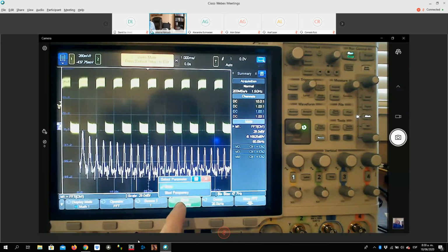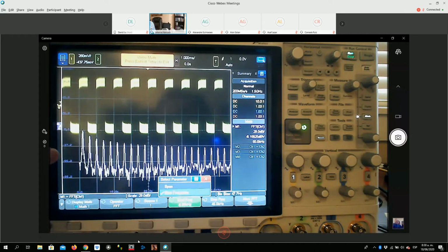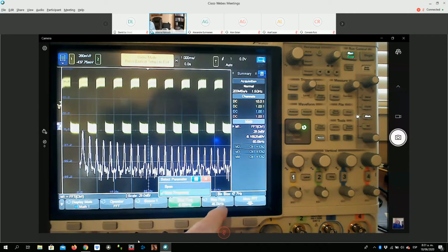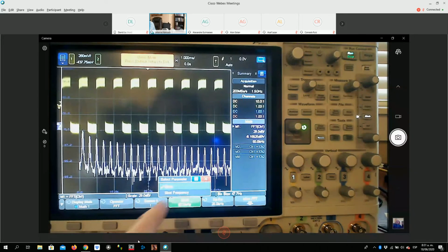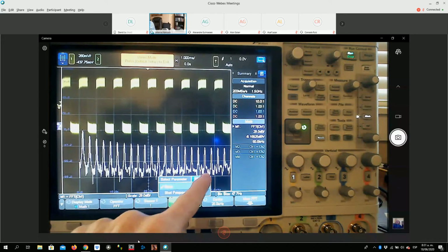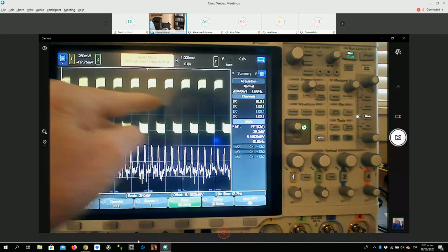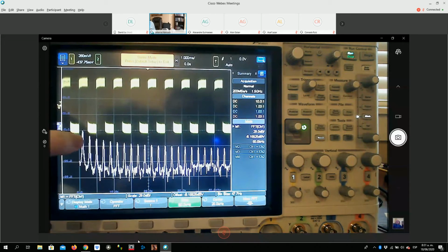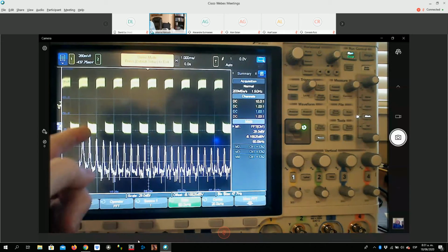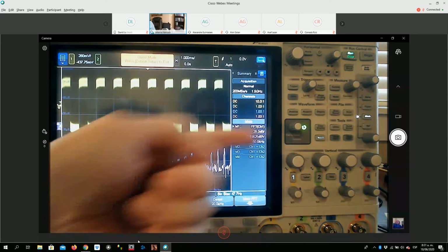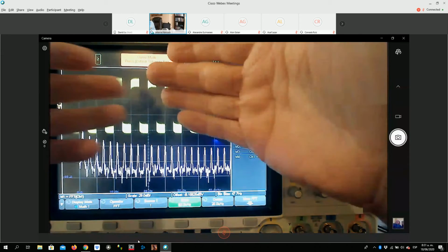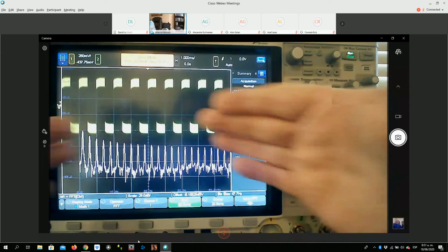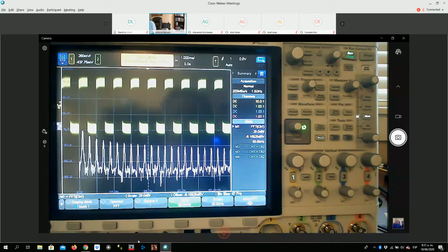Now, I also have the option of setting a start frequency and a stop frequency. This is minus 5 kilohertz, so of course you can see nothing over there. It has no negative frequency. And the right side of the display is 45 kilohertz. So let's go back to span though. So this peak right here is the fundamental of this clock. The second one is the third harmonic, then fifth, seventh, and so on, and we can see there are tons of harmonics. And as I mentioned earlier, an ideal clock signal or square wave has an infinite number of odd harmonics.